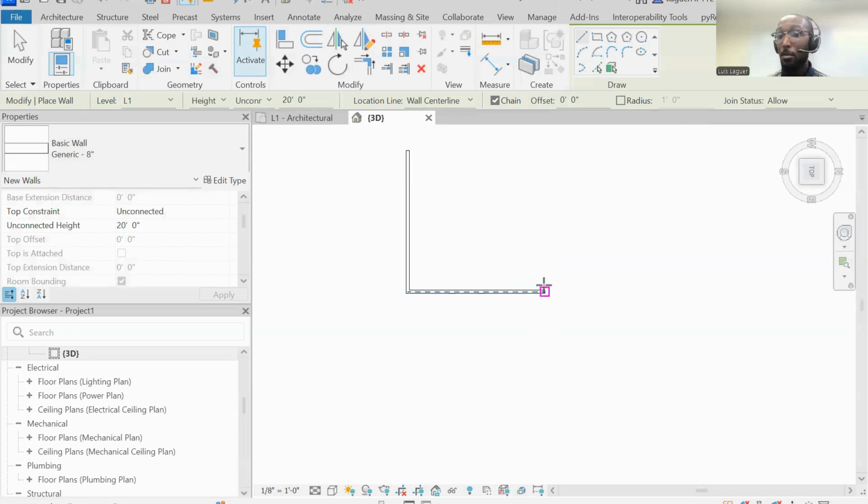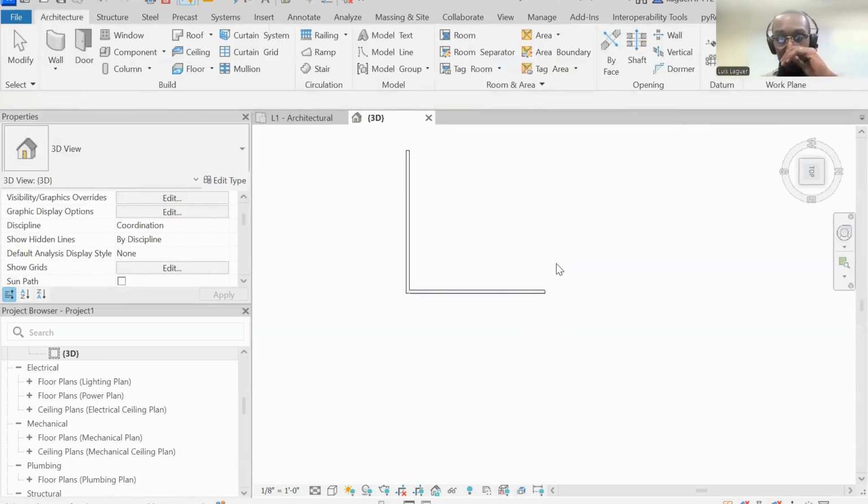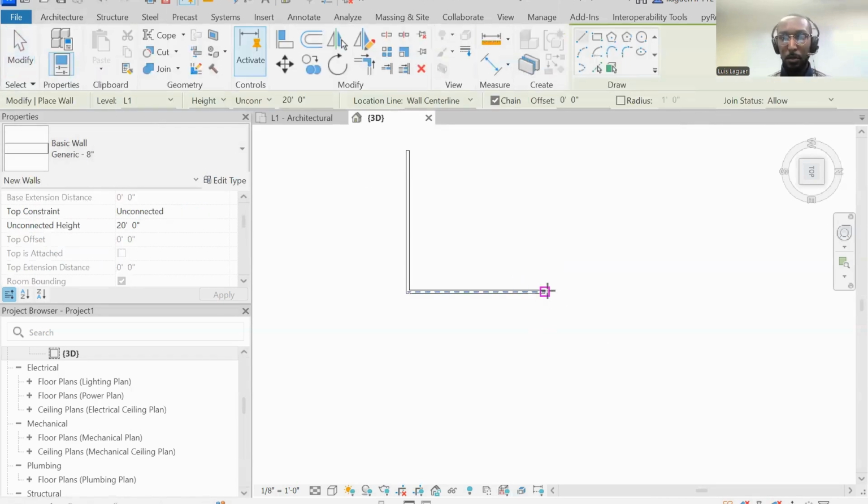I can connect another wall. You see this box right here? This is me connecting another wall. It's letting me know that if I click here, it's going to connect to this wall. That means these walls are already going to be fused together automatically, right? Or I could try something else. First option we have, of course, is to click on the wall. We go here, press one time, and then we can extend this out. And as we move it up, you see that these blue lines are guidelines.